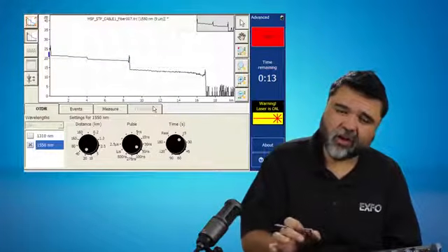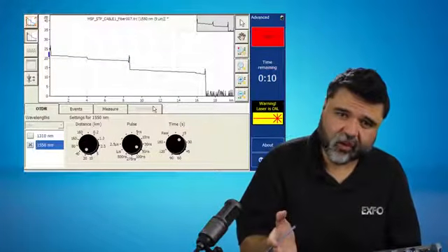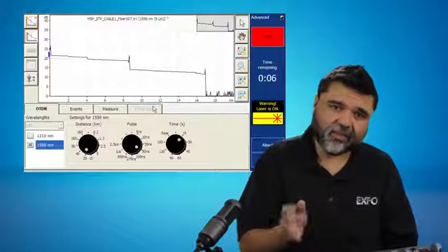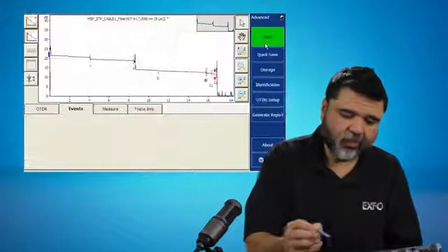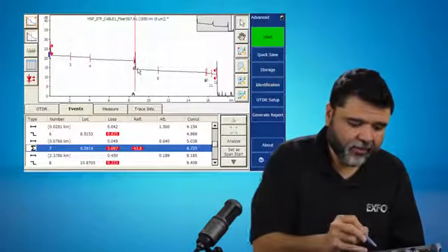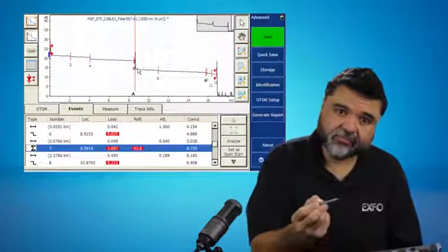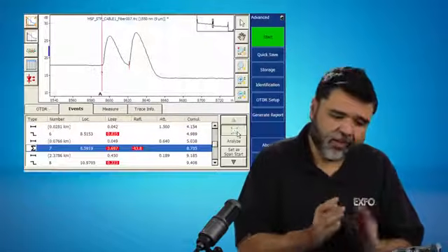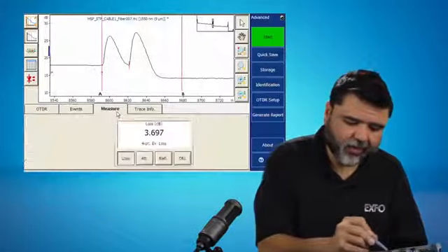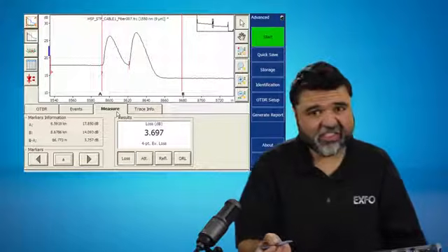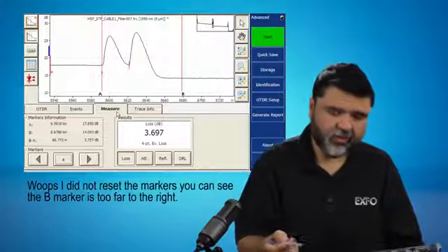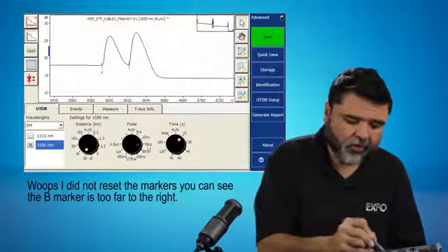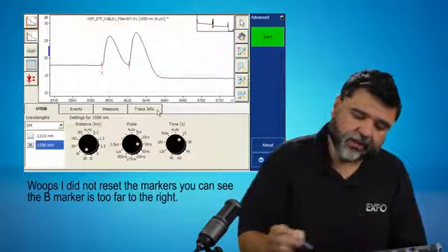It'll take a little bit longer for the trace to average out because with less power on a distance like this, I'm going to have a little bit more extra noise. I'm going to go ahead and stop it here. I'm going to find that same event at 8.6 kilometers basically. Zoom in. I'm getting a little bit tighter peaks. I'm getting a little bit better separation. My dead zone now is 86 meters. So I mean, I still have a substantial amount of dead zone here. So I'm going to go ahead and drop this down to 30 nanoseconds and retest.